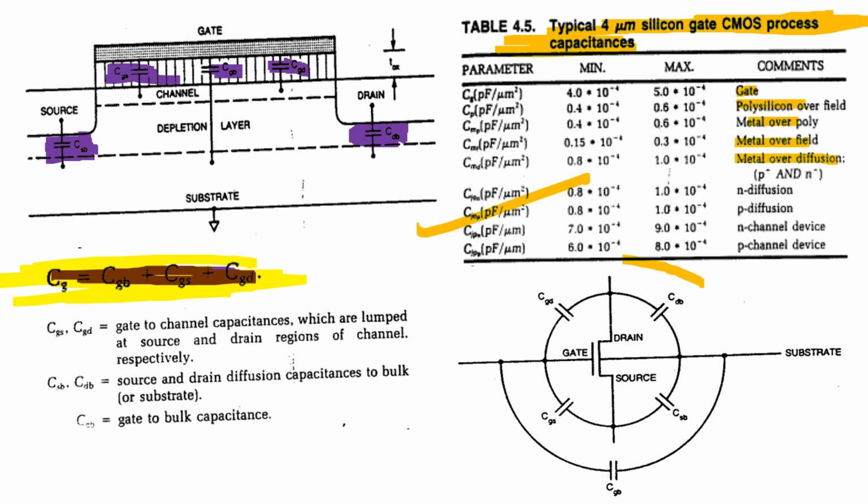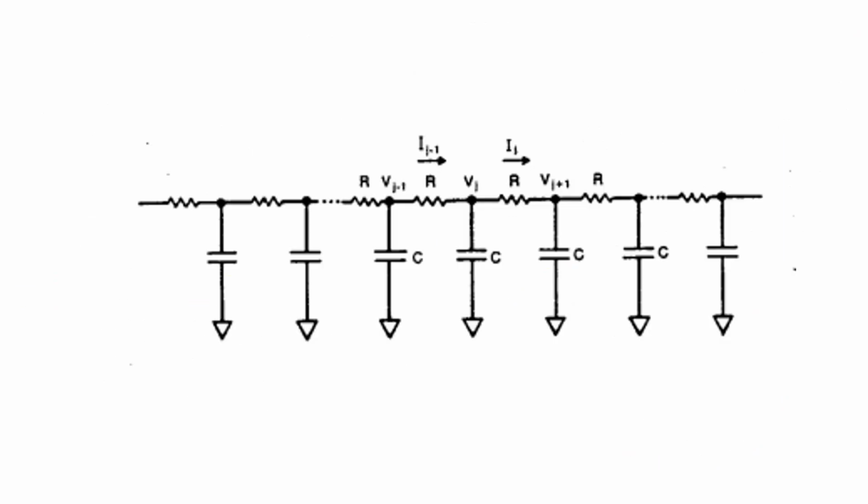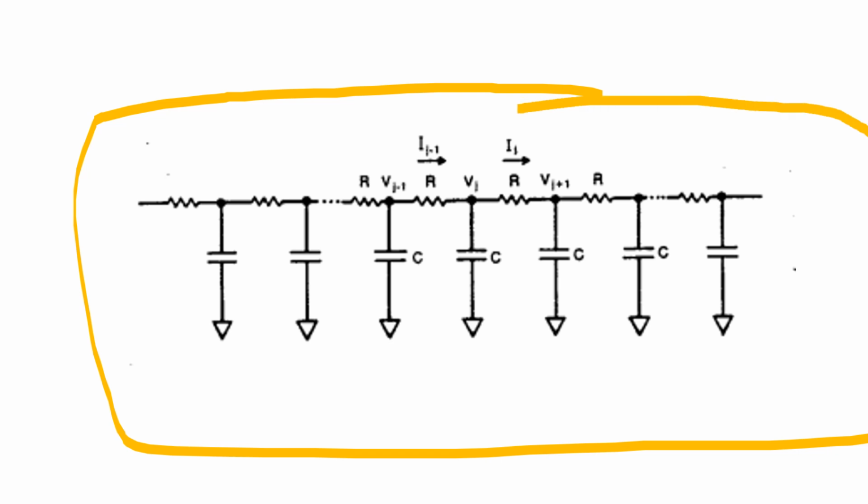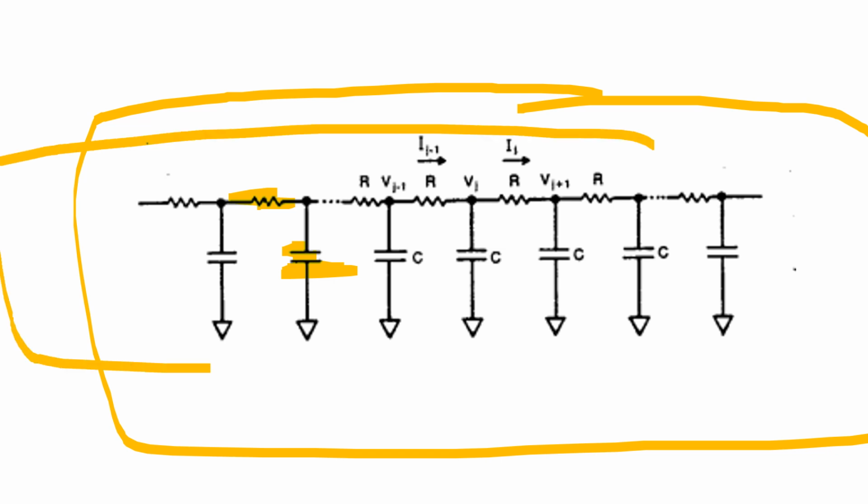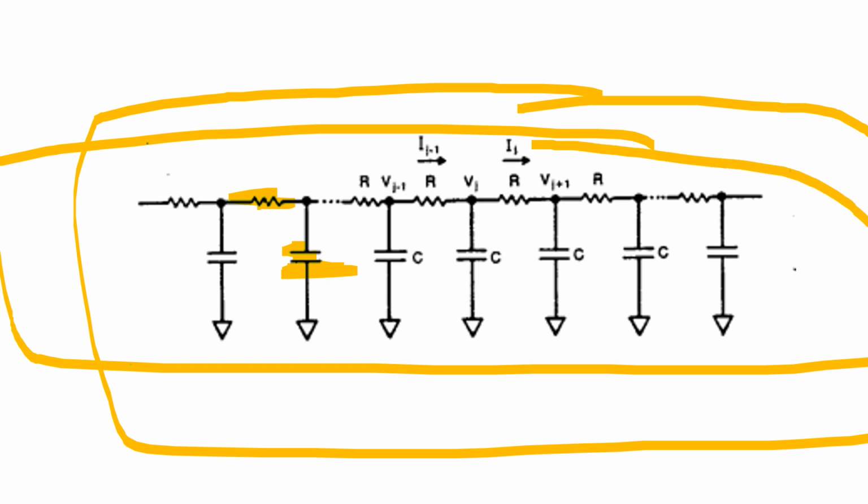I was speaking about the parasitic capacitances, which look like this. There is a MOSFET, and between any terminals of the MOSFET, there will be capacitors formed. These are parasitic capacitors. When we look at a circuit as a whole, we will see a number of resistors and capacitors, maybe in series or parallel in any combination, and we need to calculate the performance due to these R and C's, because as I said initially, T is nothing but time delay, which is directly proportional to R value and C value.